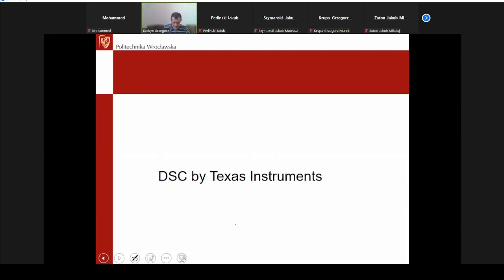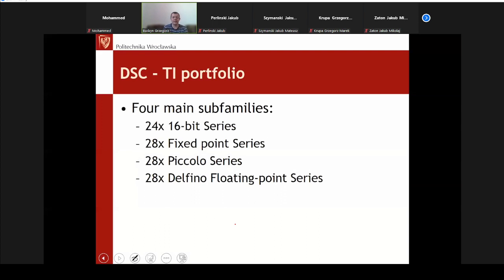Another important family, I think even more important from a practical point of view, is the family delivered by Texas Instruments. Texas Instruments was trying in the past to simplify the DSP and form DSCs coming from a simplified DSP. It was the C5000 family, which the market didn't like at all. Then they introduced a microcontroller with extra DSP features, and that's actually what the market found useful. I'm talking about the 28xx family, a family with a lot of digits after 28.